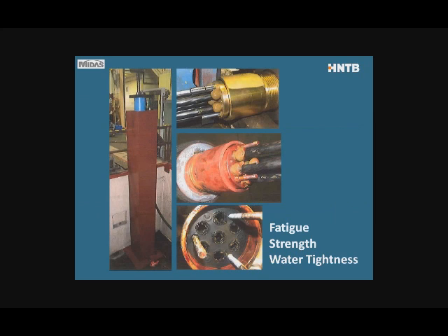Now these systems can be strained as a whole, but the advantage is that the cable can be stressed one strand at a time. So that's the difference to the bridge strand, is the one strand at a time stressing. The Post-Tension Institute has published pretty extensive guidelines for design and testing of these stay cable systems, and Blennerhassett Island was subject to the same type of testing. So what they do is that the cable gets tested 2 million load cycles to a fairly high stress range,